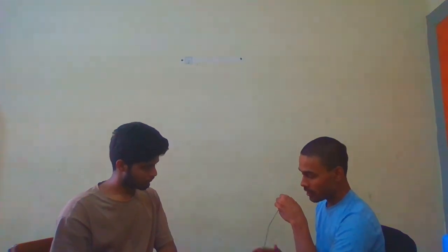The second step is to choose the direction in which the fluid is flowing. For the Cartesian coordinate system, it is x, y, or z. For cylindrical, it is r, theta, or z. Depending upon that, we have to choose the momentum flux. There are nine components in total, so we have to identify which are non-vanishing.